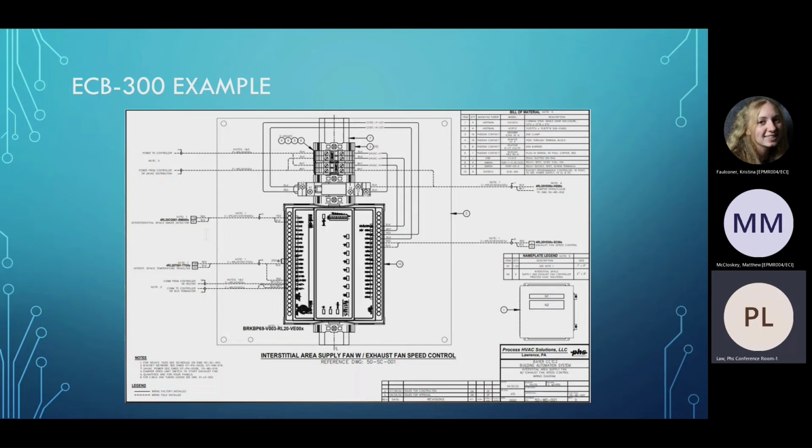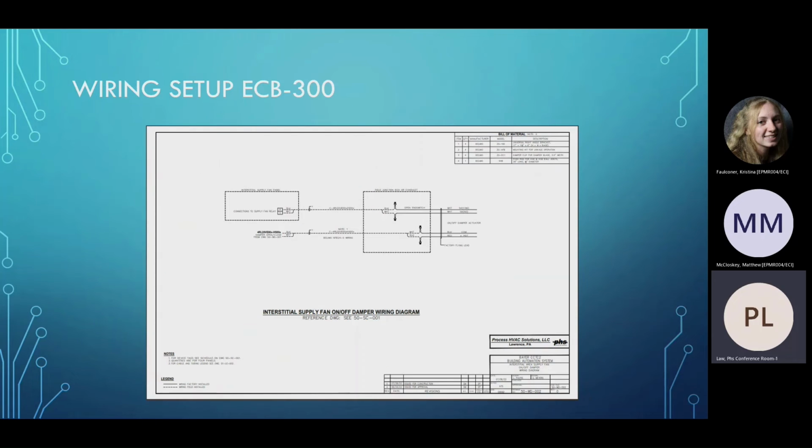It closes, but we wire a 24-volt common to the other side. And when that closes, we send a signal to a relay. This relay is in series with a damper, and the relay then triggers a fan to start. So it's a hardwired interlock. The damper has to be open for the fan to be able to turn on. And that's due to that relay right there being in series with the damper.